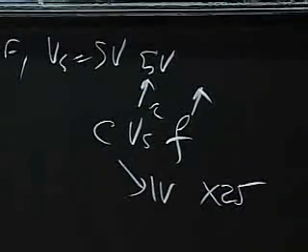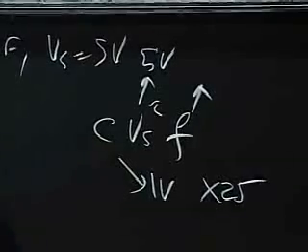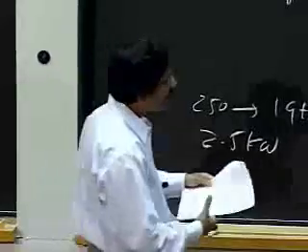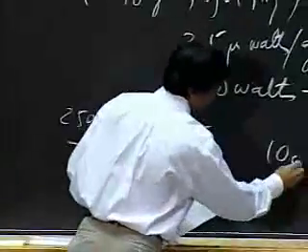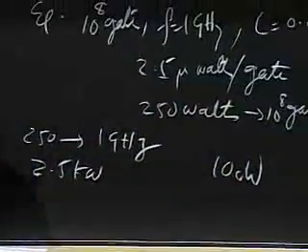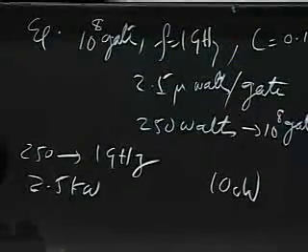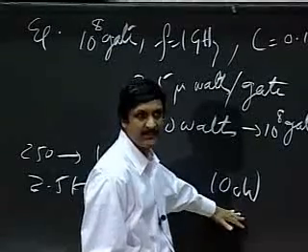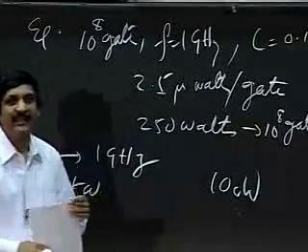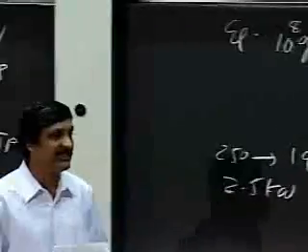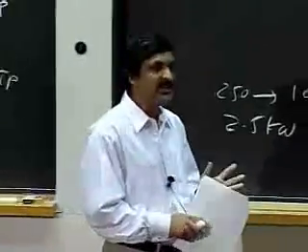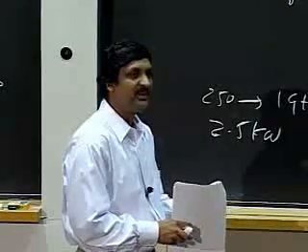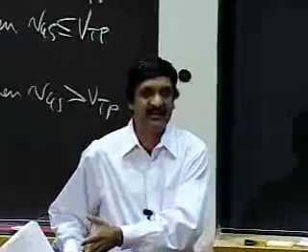Again, all else being equal, the capacitance of devices also changes as you go to smaller and smaller devices. Now, 100 watts is also pretty high, and still not good enough for mobile computers. So there are many other tricks that people use to get even lower power. One trick is to play games with the clock. Let's say, for example, in some computation you are not going to be using your floating point unit, or your integer adder unit.